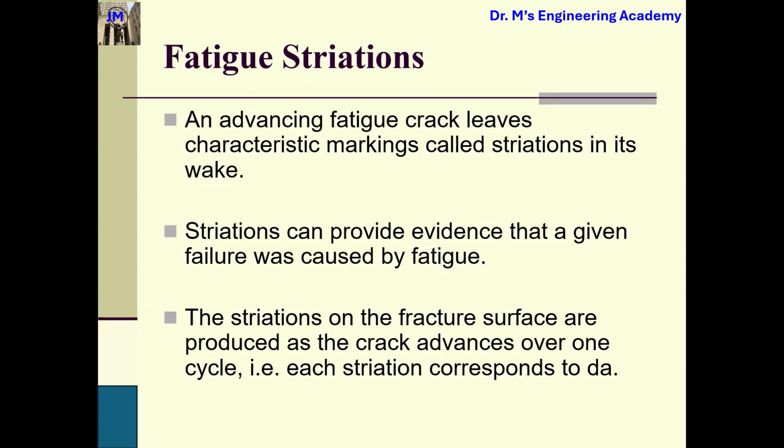Whenever you see this kind of characteristic, you know it broke because of fatigue. And the last one, the striations on the crack fracture surface are produced as the crack advances over one cycle. That means each striation corresponds to one cycle, how far it goes for one cycle.